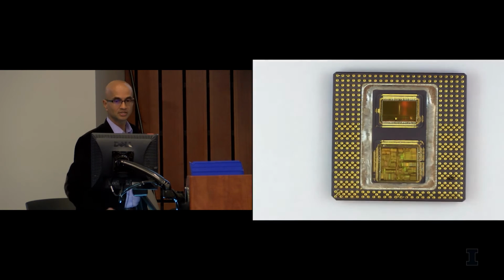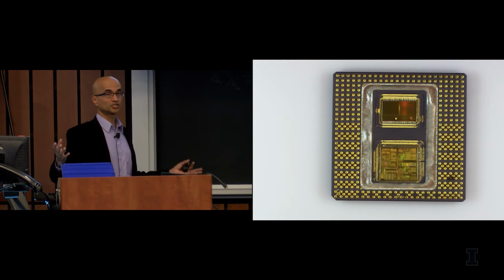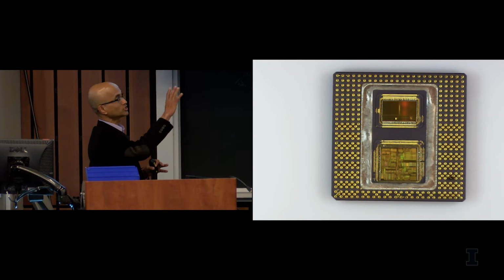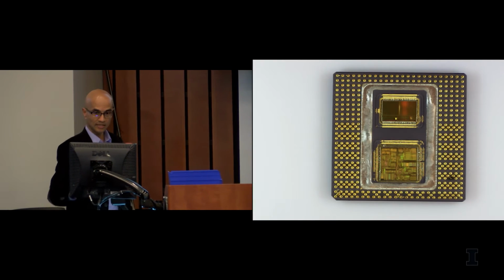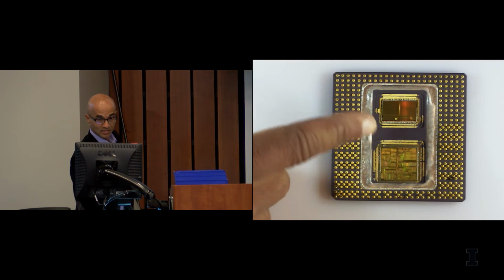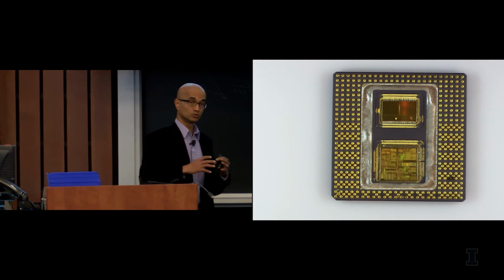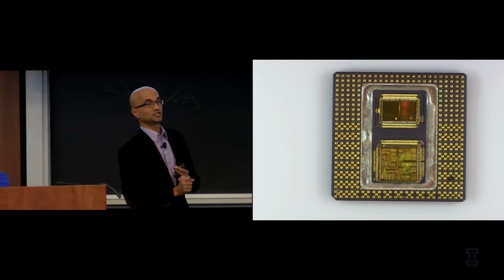And this chip is memory. It's a cache. So it's a huge memory chip that stores data. And if you were to run an application, let's say you run an app on this machine, then the traffic from this memory to this computation is going to be huge. It's going to slow your processing down, number one, and consume a lot of energy, right?